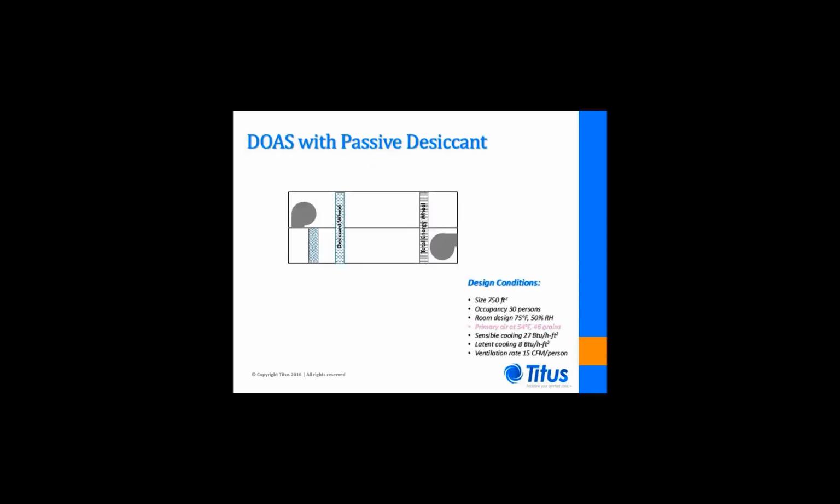This slide illustrates an air handling unit that is commonly used with a displacement chill beam system. Notice that the unit delivers 100% outside air to the classroom. It utilizes energy wheels to transfer heat and moisture between the supply and return air streams, but never mixes the streams themselves. This type of air distribution system is referred to as a dedicated outdoor air system, or a DOAS system. Outdoor air is immediately introduced to a total energy wheel where heat and moisture from the outdoor air is transferred to return air that is then exhausted.